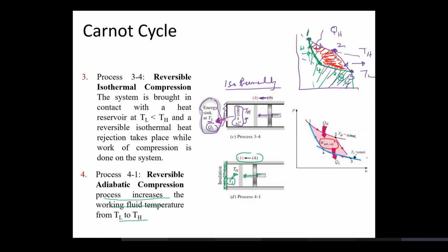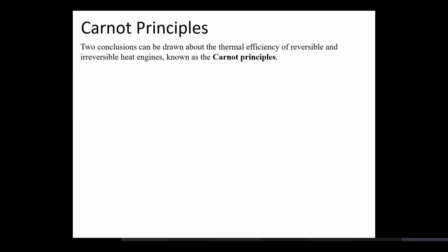Yes, sir. All right. Now, based on the Carnot cycle, two principles have been developed. These principles are very important to understand. The first principle, these are called Carnot principles, and they are about the thermal efficiency of reversible and irreversible heat engines. By the way, if I ask you, do you expect the efficiency of a reversible heat engine to be more or an irreversible heat engine to be more? Reversible, sir. Reversible. All right.